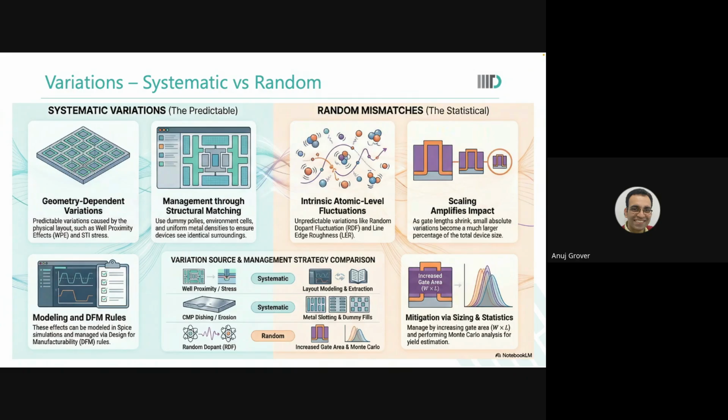again, it is closely linked to the physics, and we use stressors carefully. In fact, silicon germanium is used to stress. So a very slight doping of germanium is done in silicon atoms. Now, what does that do? Germanium atoms are larger than silicon atoms. This you have done in your class 10, 11th, 12th physics also? No.